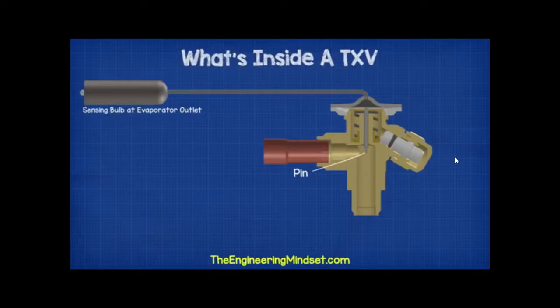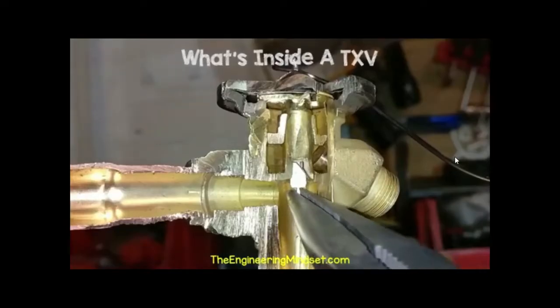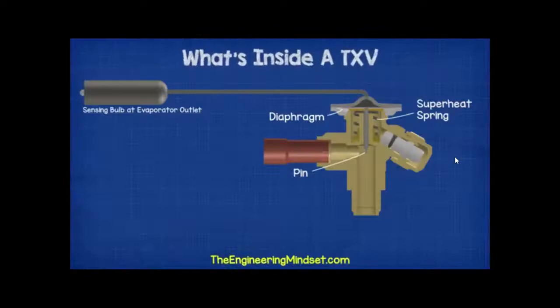Well, we can see this small pin here. This is connected to the diaphragm up in the power head. The diaphragm is a thin sheet of flexible metal. As the diaphragm moves up and down, it causes the pin to move up and down also. Underneath the diaphragm, we have a spring which is pushing up against the diaphragm. We can use this to adjust the superheat, and we'll look at that a bit later in this video.